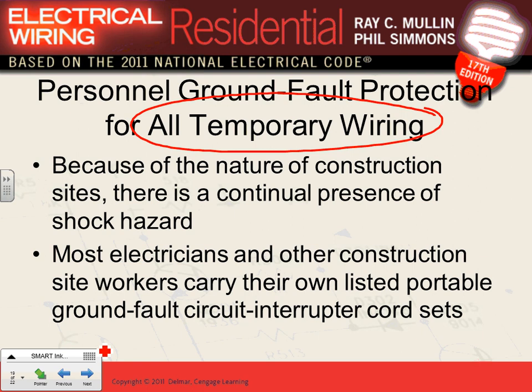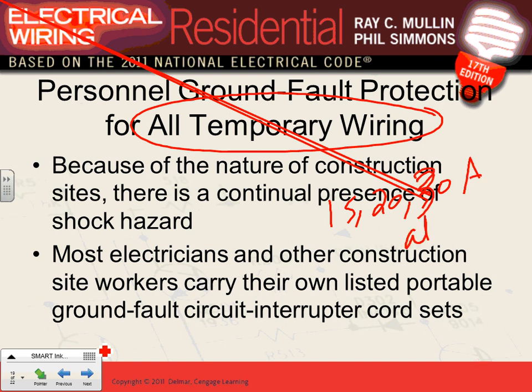The code says the following, guys: 15, 20, and 30. Oops, look at that, 30. 30 amps, believe it or not, at 120 volt have to be GFCI'd. These receptacles at 120 volt have to be GFCI'd in a construction site. 120 have to be GFCI'd.